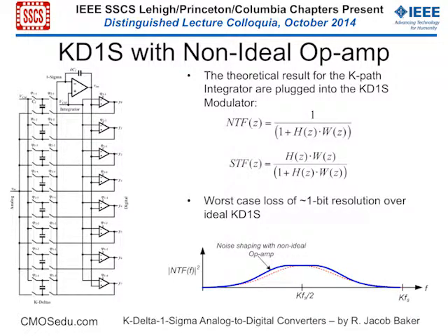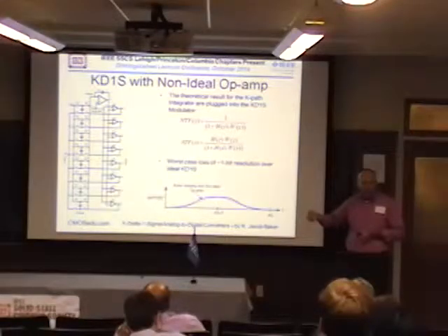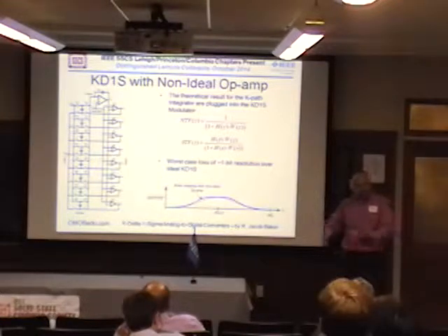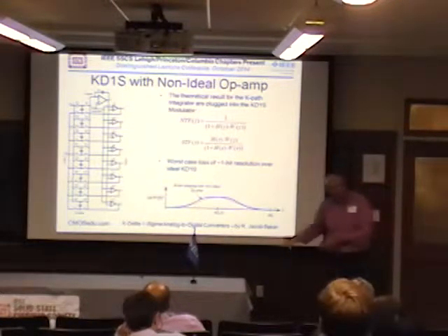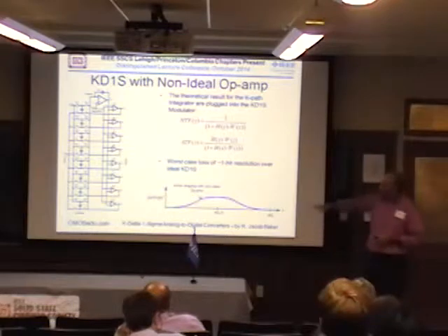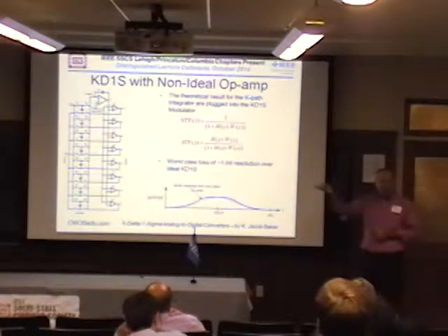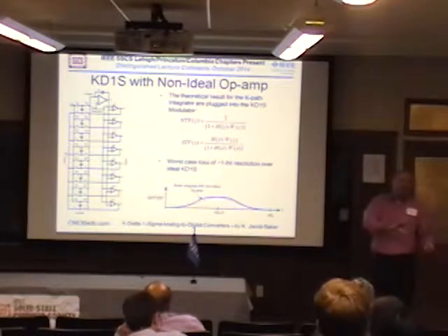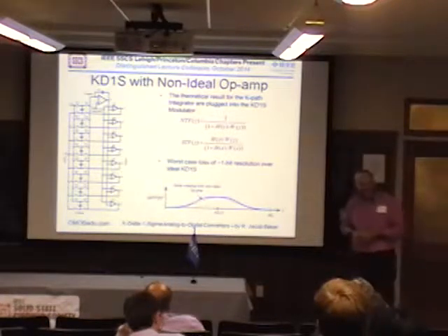Yeah, but even so, the different size capacitors are an issue, because then you're feeding back different signals since your effective cap size is changing from one use to the next. But in the case of the noise, that still wouldn't matter, because if you used a bigger capacitor, you just get less kT over C noise, and then you dump less noise back in. Yeah, but it might affect the distribution. Yeah, it's just unobvious.